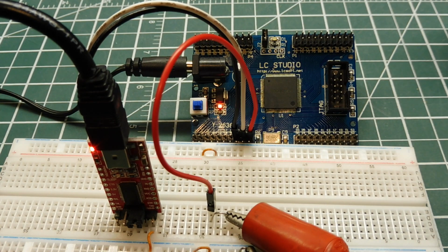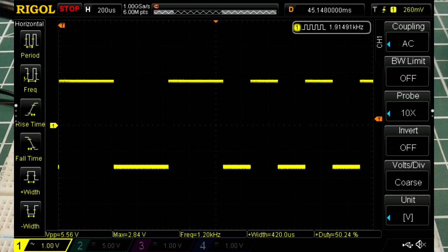So those are the data being sent, and if you look at the scope, you can see the transitions between the mark and space, that it completes a frequency cycle on its transition, so we have zero crossing synchronization.